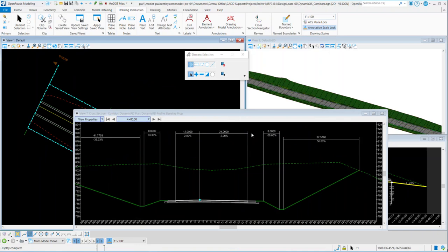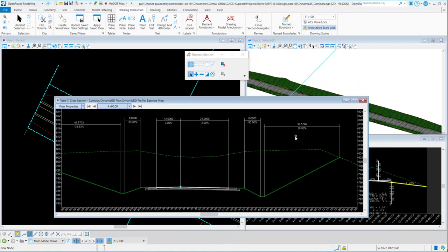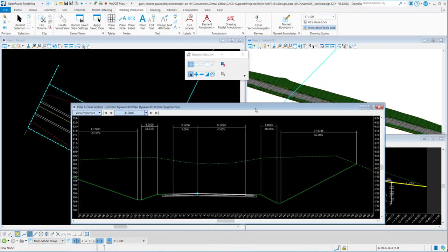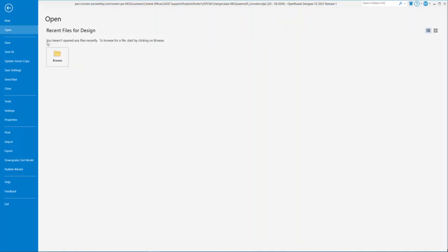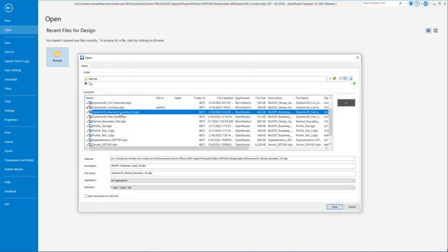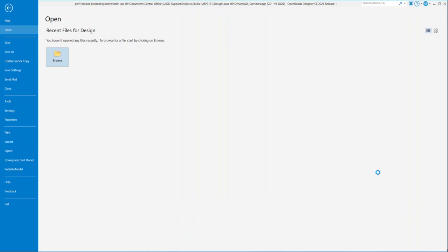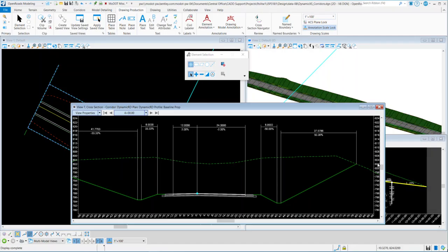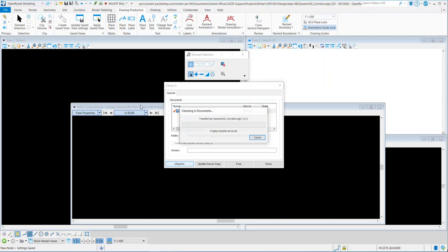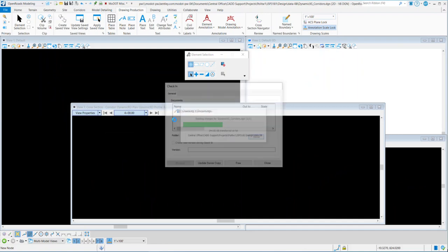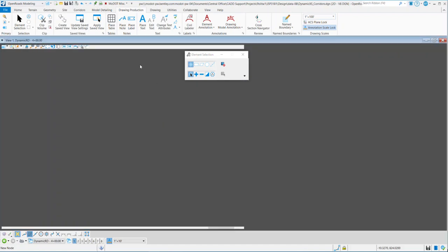And you'll see in the dynamic cross sections what we've changed. We've changed that pavement width and these couple of slopes here. So at station 4+00, where I'm at, you can see what's going on. So once that's been changed, everything's been edited, we go back into that name boundary with the cross sections. So we'll browse, name boundary cross section for the dynamic cross section. We'll open it up. We'll check in our changes. And we left it at this, I believe, yeah, 4+00.